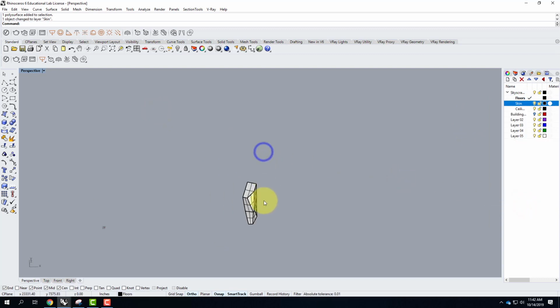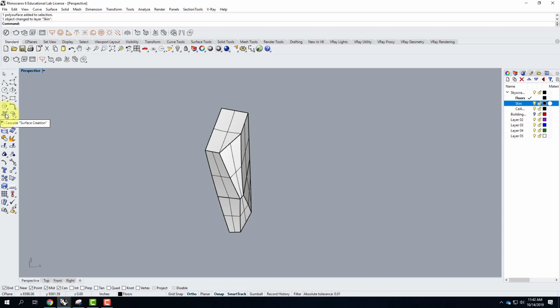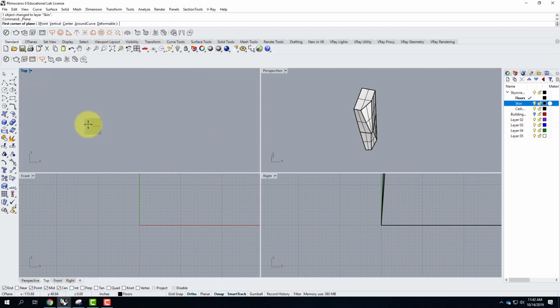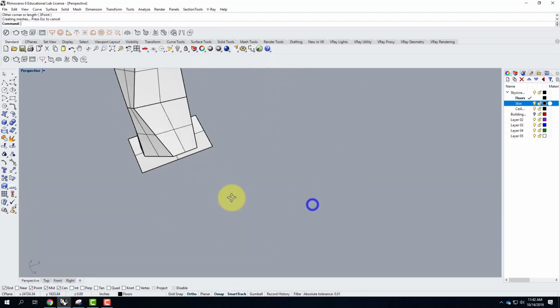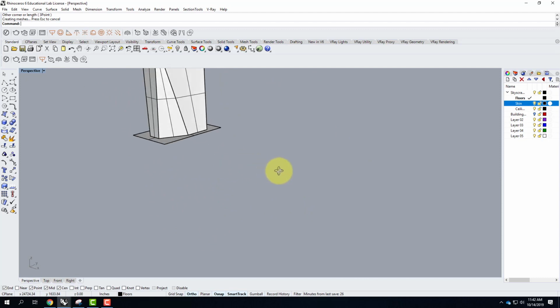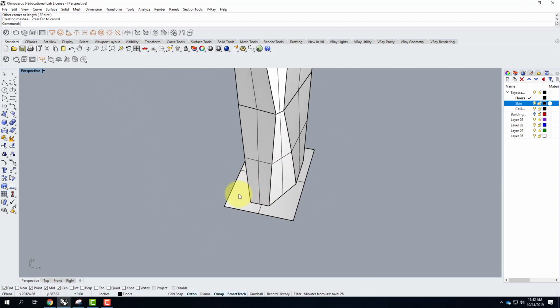And to create the floors, I'm going to create a rectangle. It'll just be a rectangular plane, corner to corner, that is larger than my building footprint. So I'll look at it in the top view. Usually that's easiest. And just make sure that this is larger than my building footprint. There it is. So if I'm creating these floors, I need to know where these floors occur. And part of the reason I gave you the size is so that we can define these relatively easily.